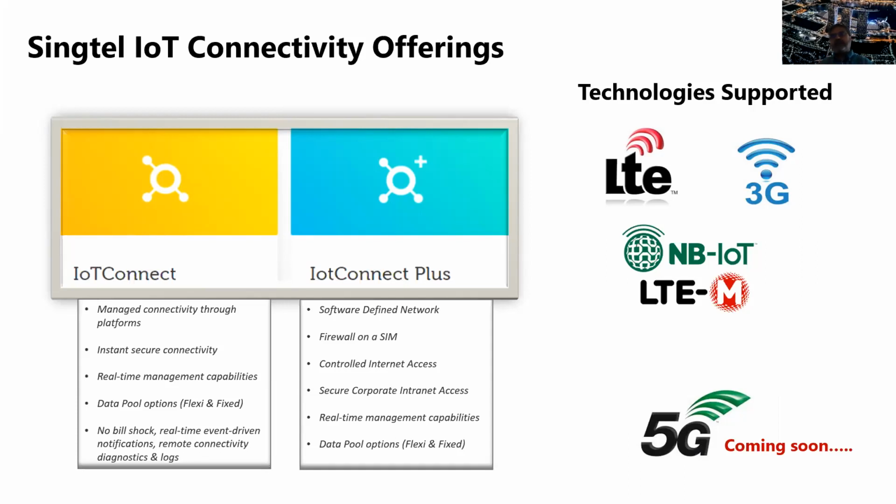For us, the perspective is this: NB-IoT is suitable for applications where your data transmission is limited on a daily basis, because that's where the concept of battery conservation comes into the picture, right? You don't want to have a chatty application with NB-IoT. If you're expected to send data every 5 seconds or even less than a minute, it's still very chatty.